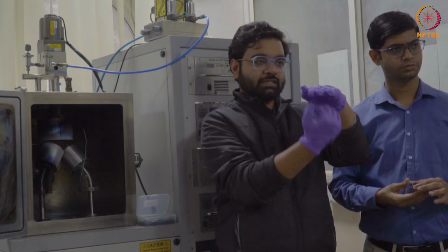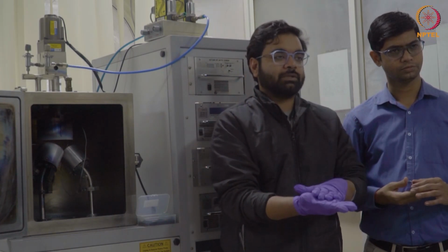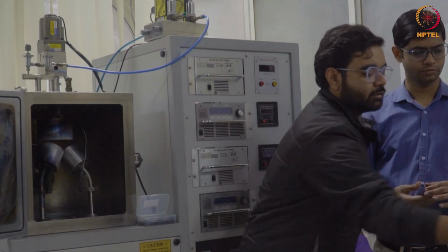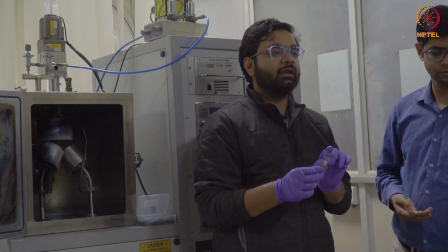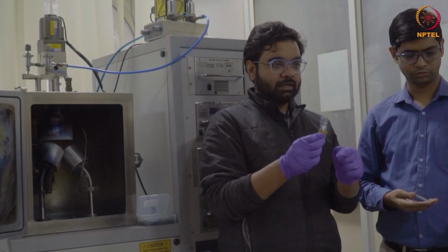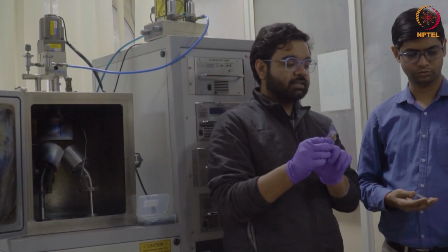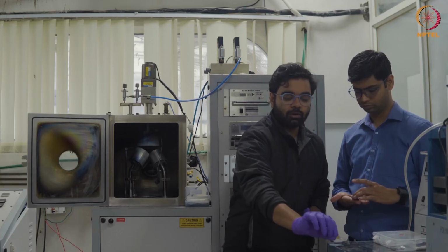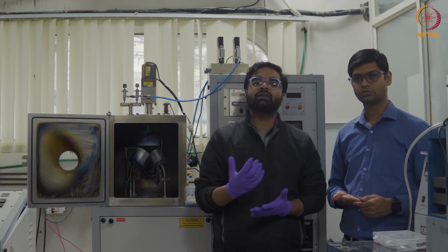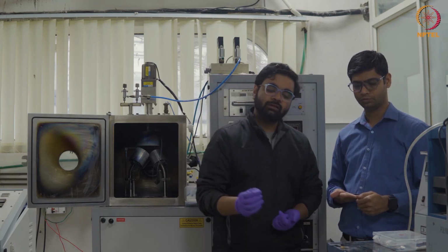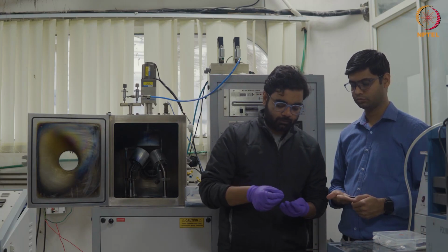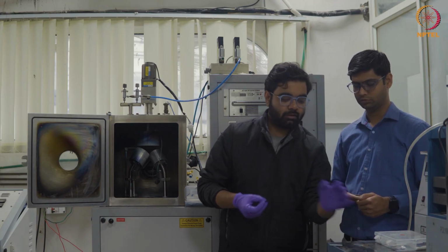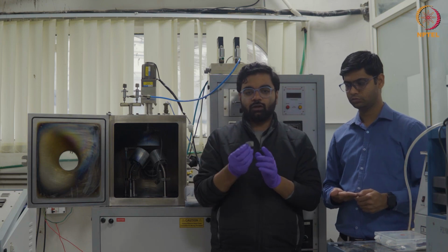The material, once it ejects from the surface, comes onto the base substrate. The base material is the acceptor substrate. As you have seen in this case, this is a flexible PET substrate, wherein we observe that the material transfers and comes onto this flexible PET substrate. Now this does not mean that the technology is only focusing on the flexible substrate. We can even do these kinds of printing on a solid substrate. Like if you see in this case, this is a solid silicon substrate.